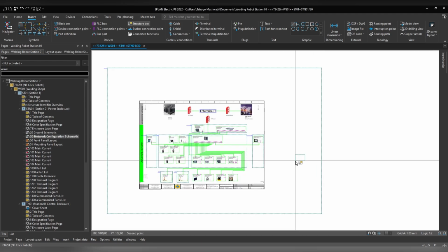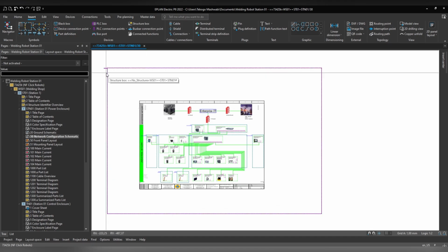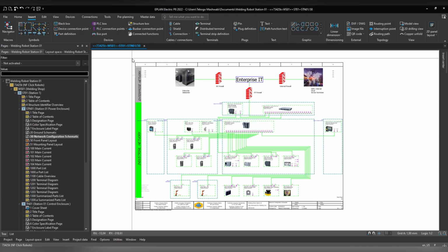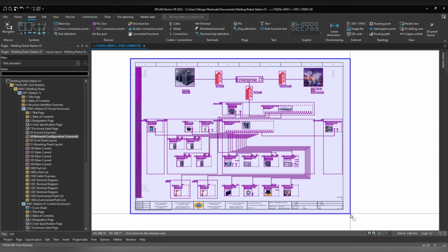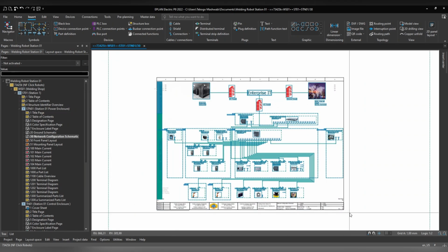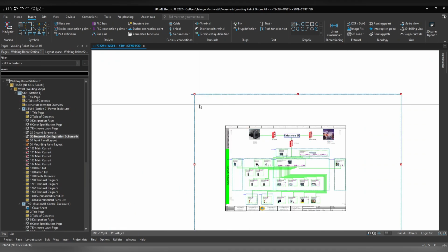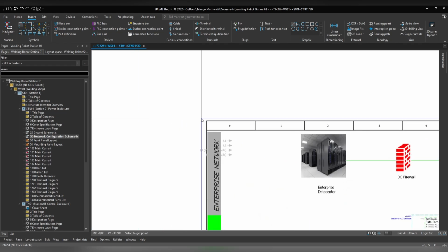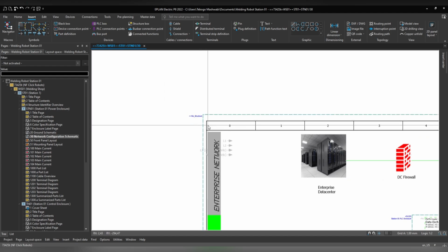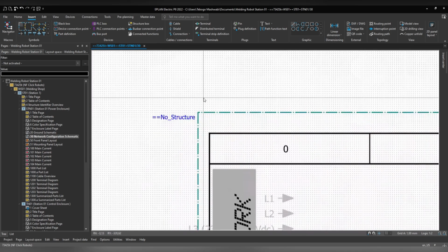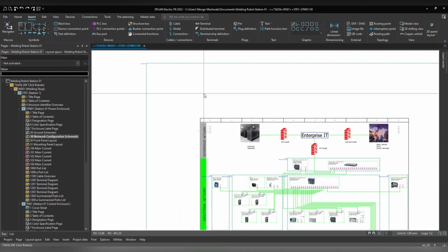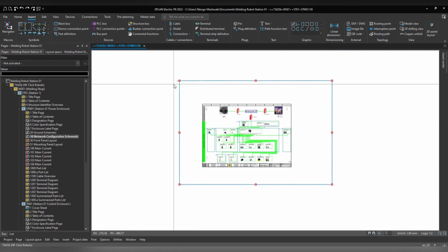And right there, we should have something like that. So the reason why I make it so large like that is because when I print out these drawings, the printing function will only focus on this little bit of area. So it will actually not see that line there. That's why I have it so large. If you have it so close to the schematic, when you're printing, the printing function will be able to see those lines there. So that's why I'm pushing it way out of the schematic.